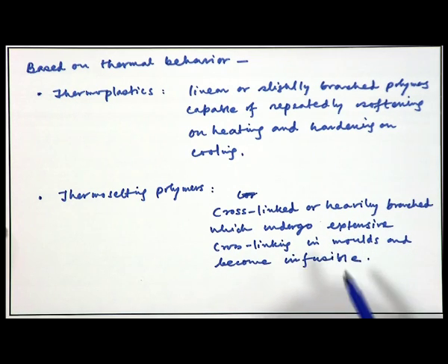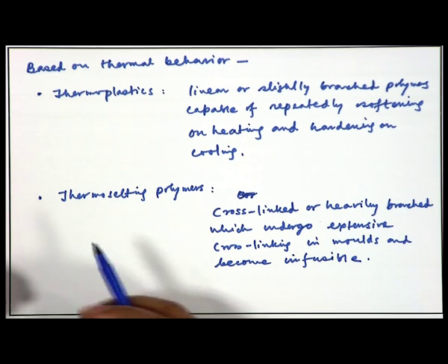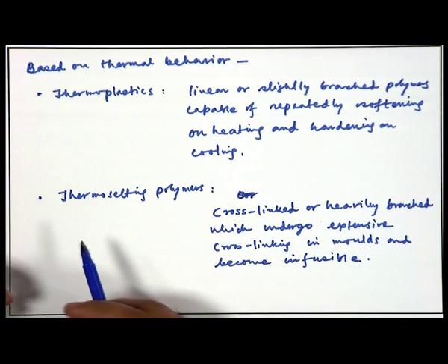What does it mean? In this case the polymers have cross-linkable groups. You heat it up, and the chemical reactions which create the cross-links between polymer chains take place, and when you cool down, it will occupy the shape.